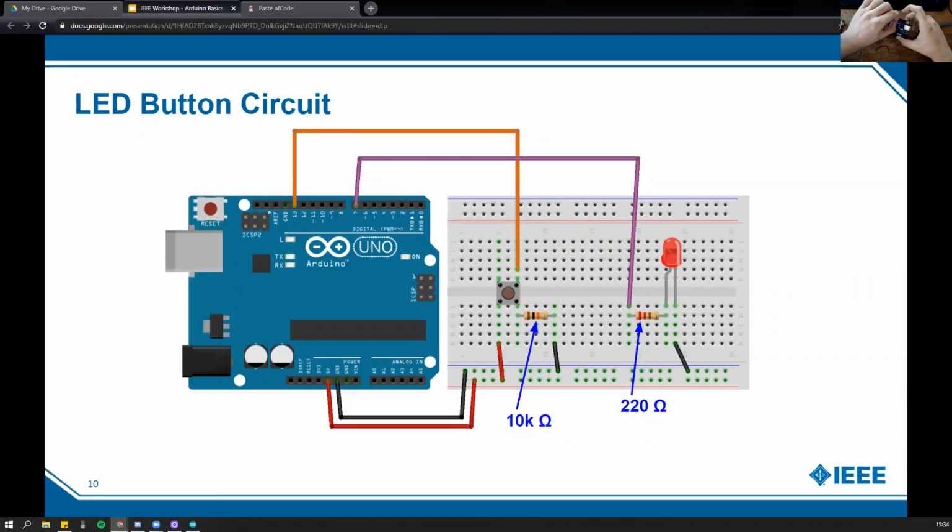You want to make sure that you connect it to pin 13 and not the ground above. I've had that trouble before, and it doesn't really do any harm. Your circuit just won't work, and the Arduino will turn off because you're shorting it to ground. It doesn't really harm the Arduino because it has some built-in protection, but it's something to keep in mind. So if your Arduino just turns off when you're building the circuit, that's probably why. Just check whether your wire is on ground or actually on pin 13.